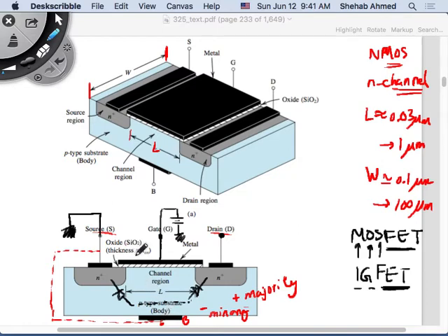So if I put a voltage here, that's positive, and this is ground, right? What did I create? This is an insulating material between them. So I have a potential, an insulating material, and another potential further away. An electric field, because I have something like a capacitor. So I've created an electric field due to what? Due to this gate, right?